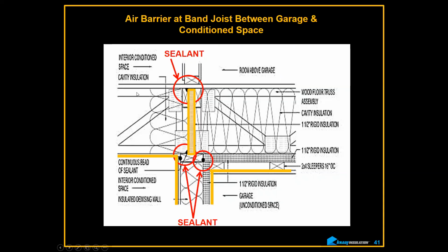Inspectors, sorry to interrupt you, Rick. I want to call this one out because I see this missed in the field all the time. That wall separating the garage from the house, inspectors, just a fibrous material here does not meet code. You have to have a rigid material that is sealed. Sorry to interrupt. Keep going. No, that's great. That's terrific. It's a really good point.